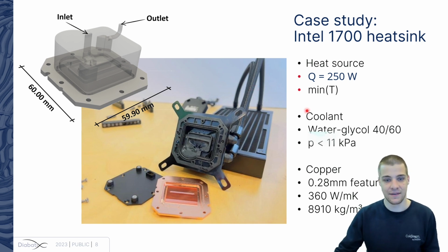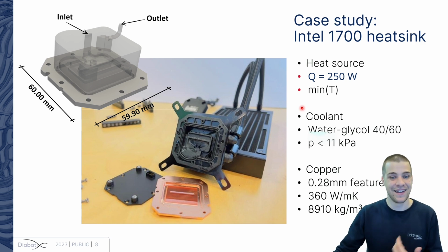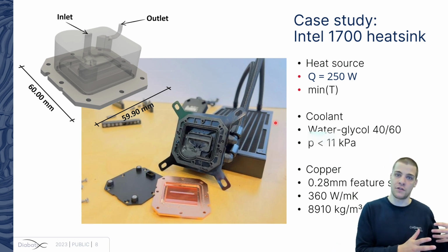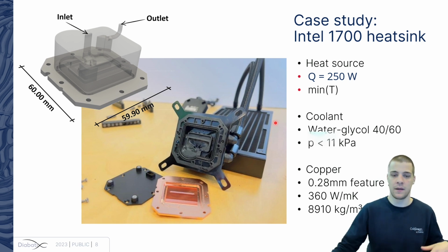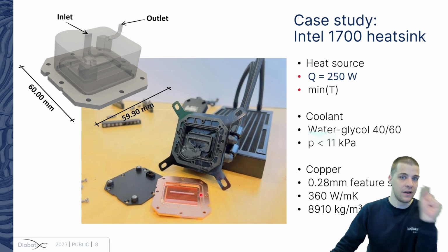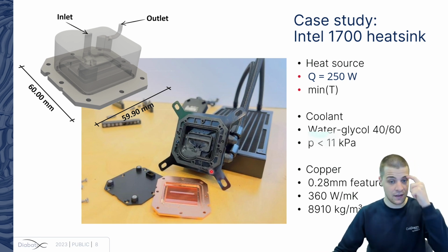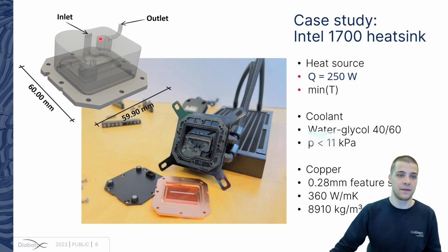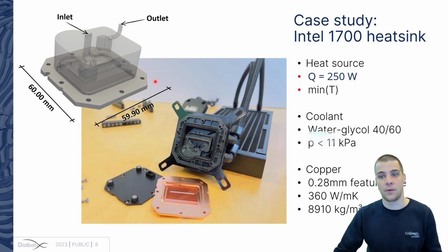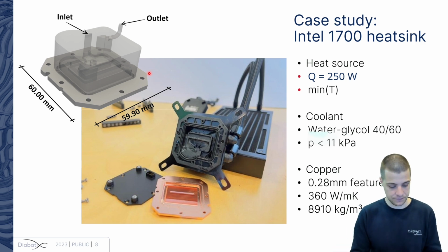All right, now that we know what generative design is, we can apply it on a case study. And as you know from the title, we'll cover a CPU cooler. So basically what we did is we bought a commercial off-the-shelf component, quite an expensive one. We took it apart, as you can see here, where we noticed that the conventional design is basically skived fins, so very narrow fins, and they are very closely spaced. And that's something that we then redrew in CAD and let it optimize by our software.